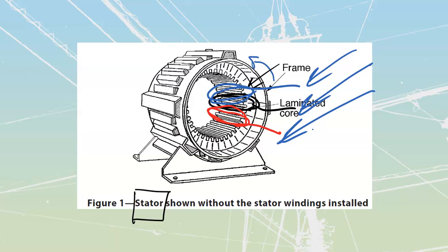It says that the three-phase stator windings are made up of 3 single-phase windings placed 120 electrical degrees apart. By 120 electrical degrees apart, they just mean placed a third apart. Okay, there's not necessarily going to be only 3 windings. It could have 3 windings. It could have 6 windings. It's going to have some multiple of 3 because we need to have an even amount per phase inside of there. But it could be composed of many of them that are just alternating around, or relatively few that are once again alternating around.